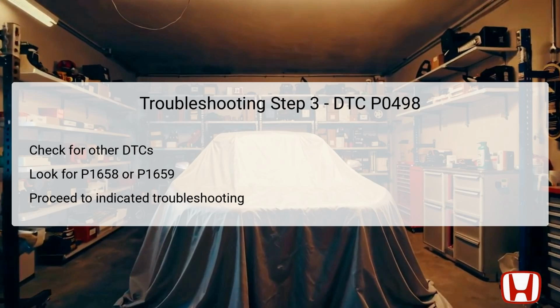If either of these DTCs appears, the technician needs to redirect their focus to the suggested troubleshooting for these codes, as they may indicate additional electronic control issues that could compound the situation. However, if no additional codes are found, one can move on to the next step of troubleshooting regarding potential fuse issues. Having a clear picture of all potential faults is crucial to resolving the P0498 effectively.